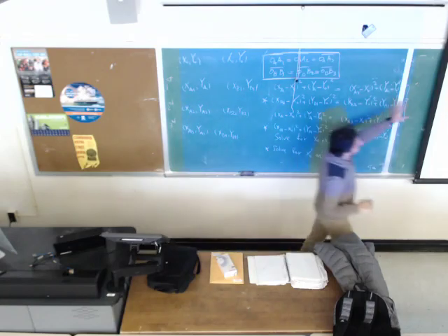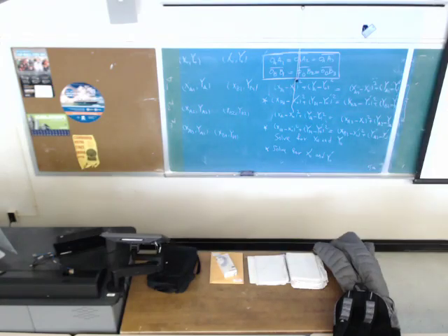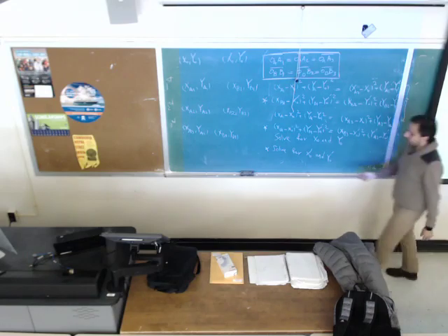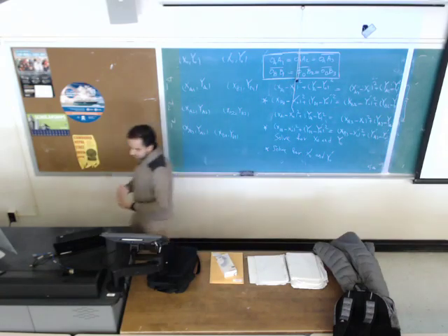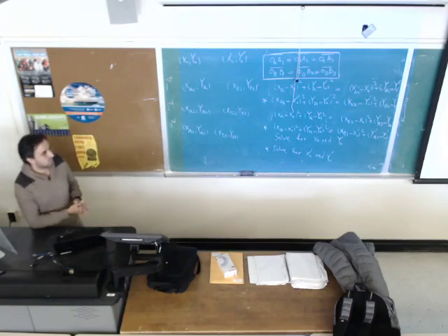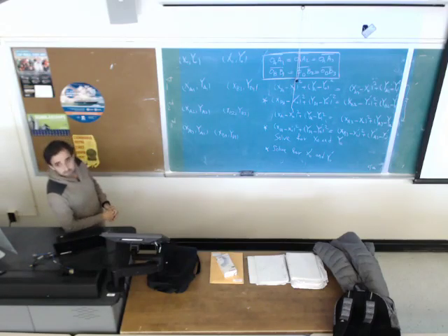And the second system of equations is going to look like this. Same as the first set of equations, except here we are going to change a to b, and x_o and y_o to x prime_o and y prime_o. So we have two equations for now. We are going to get the coordinates of joint B.